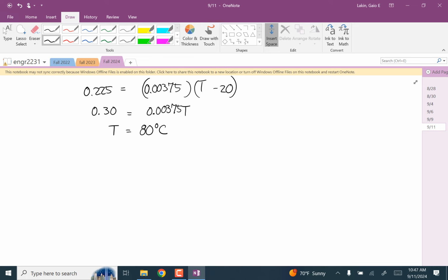In either case, electricity leaving your system is considered doing work, and electricity coming into the system is considered work being done on the system. So electric work is always going to be external, not the change in internal energy. If electricity is being generated and leaving the system, you represent that as work. Cool. Thank you.